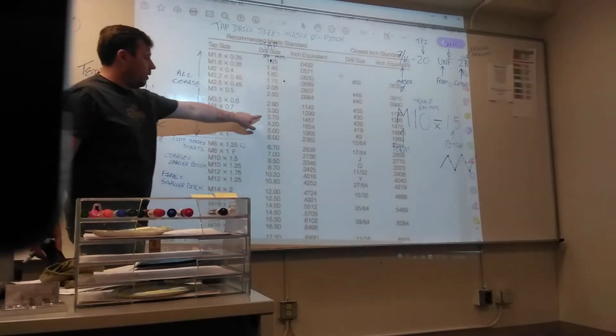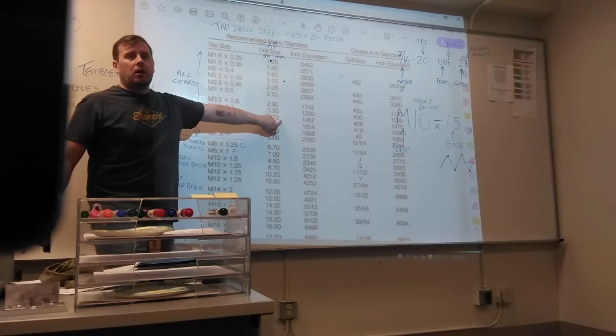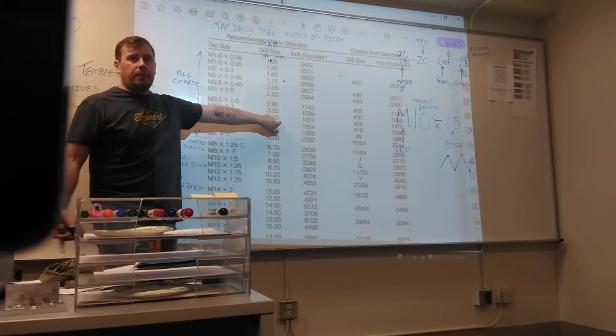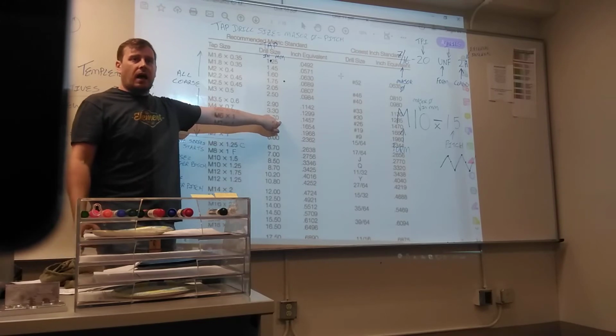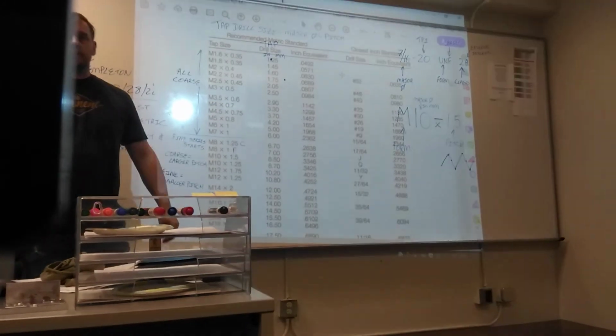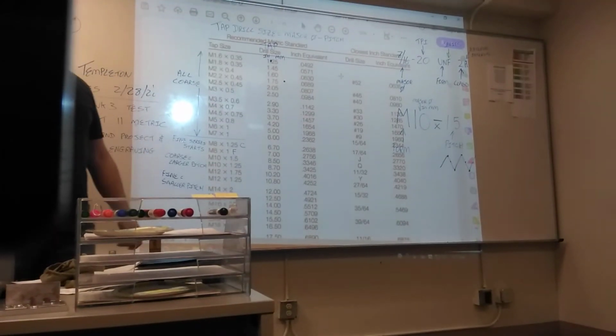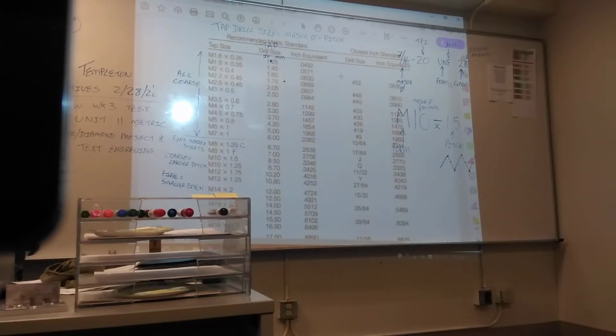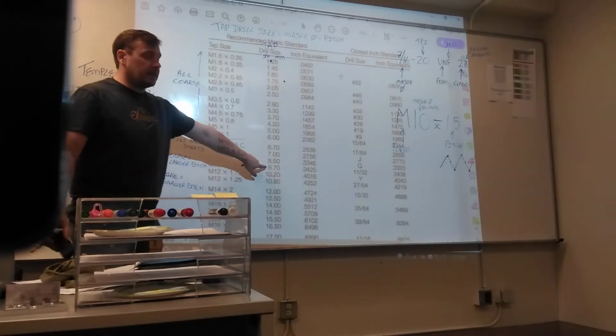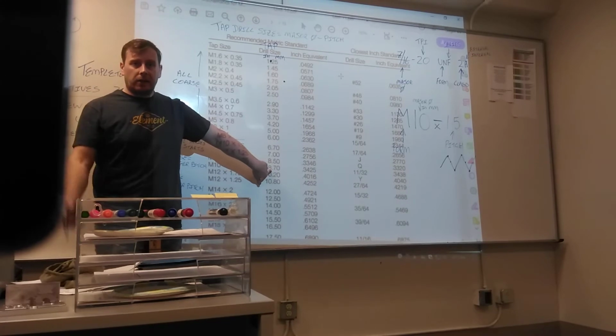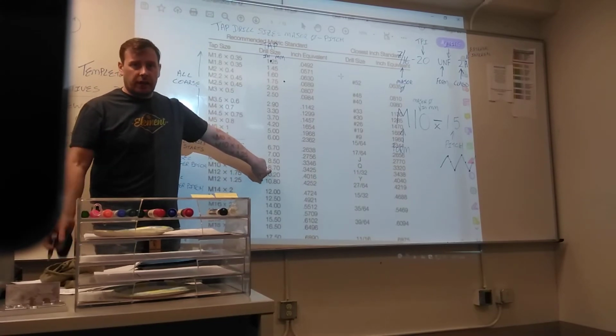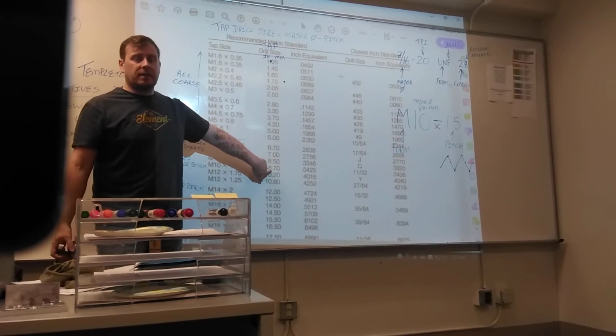But if you want a 3.75 drill, you've got to pay more money, it's custom. So people just drop down to the nearest size to drill it out. Like the M10 by 1.25, that should be 8.75. But now you've got to buy a custom drill, so they just say, let's just drop down to 8.7.